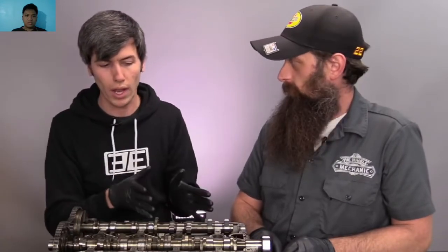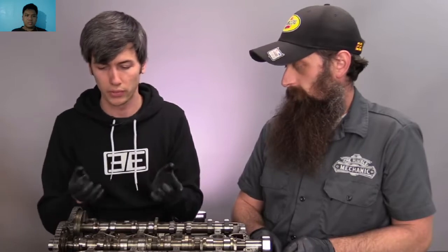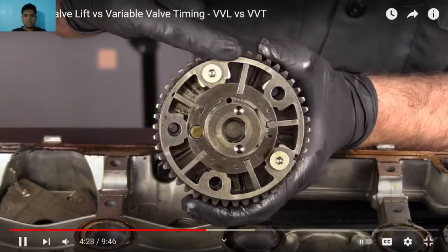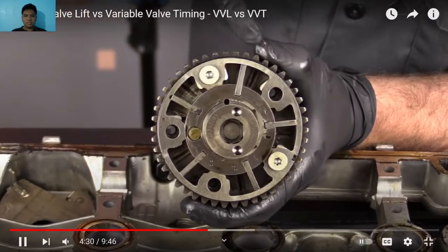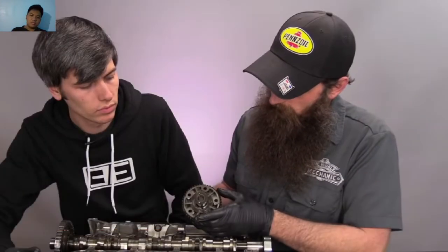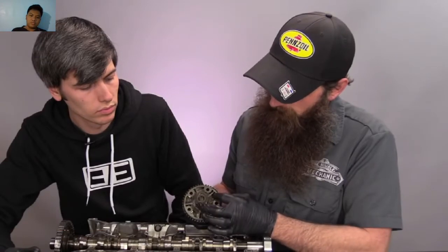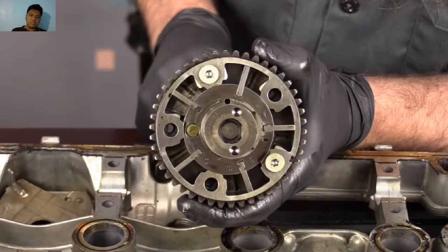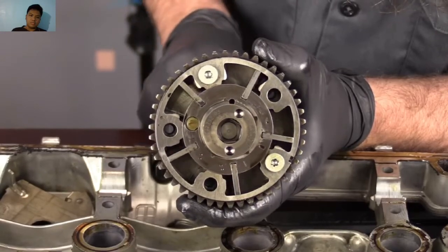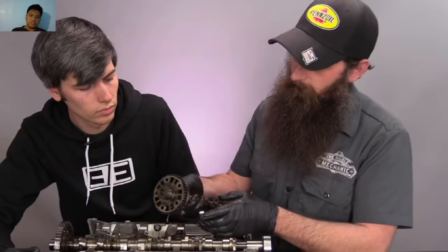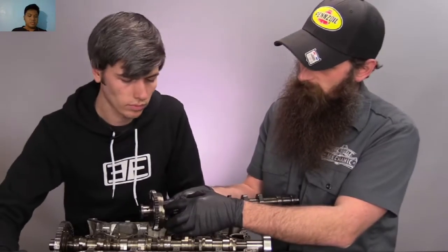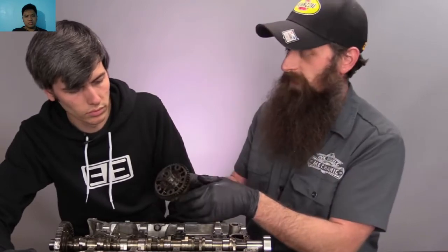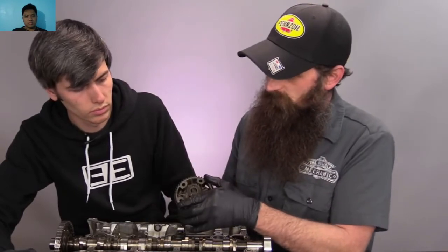We're going to talk about why you would want to shift when the intake valve opens and closes, but first let's take a look inside and see how this works. The variable valve timing is all based on oil pressure. When the profile wants to change one way, the well will fill up here and shift this way. If it needs to shift the other way, there's another port and it'll shift this way. And when it wants to bleed down the pressure, there's a relief hole right down here at the bottom. Then this oil will fall down the timing chain side and it'll reset back to 0.